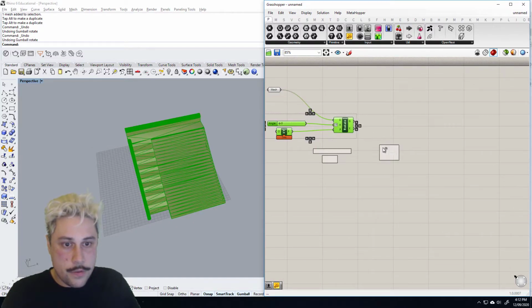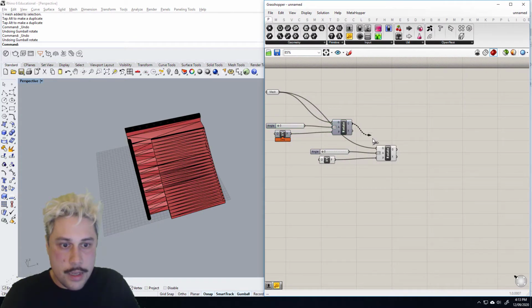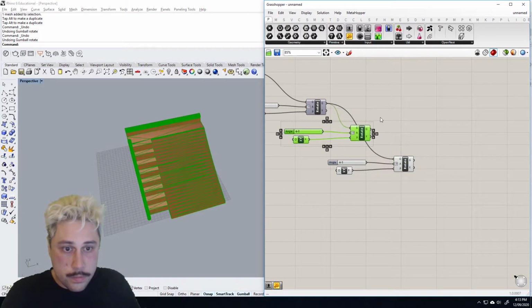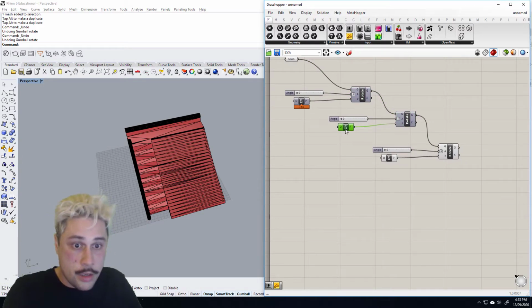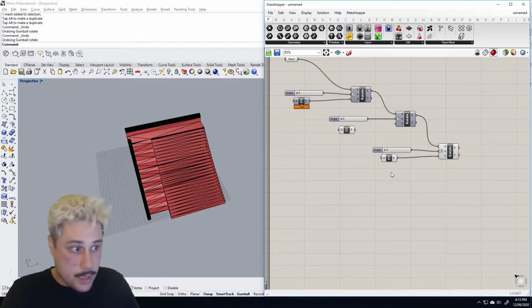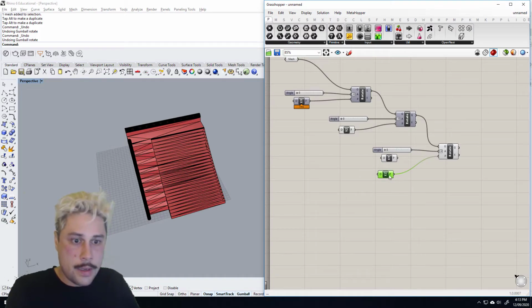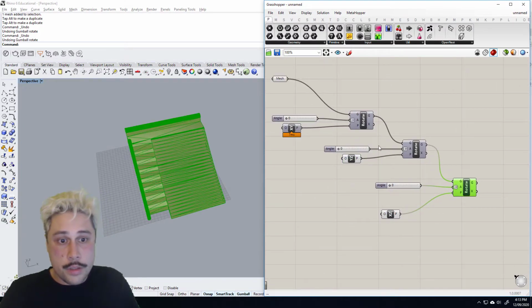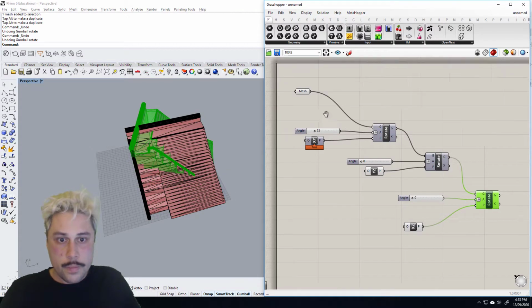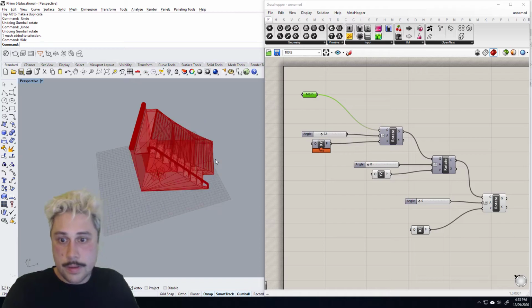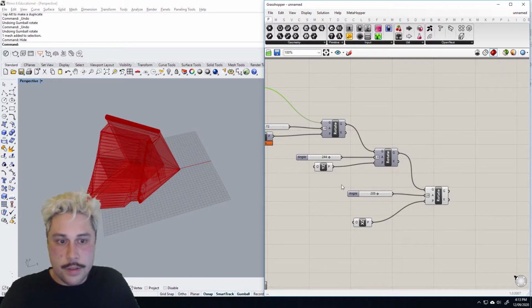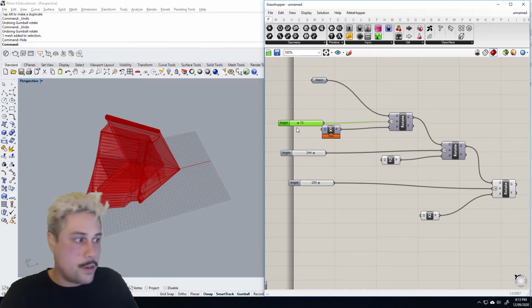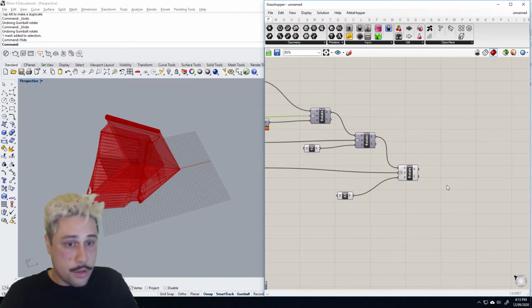And then we're going to daisy chain a few of these together. We're going to take that result and rotate it, except we're going to change the plane to be YZ and then XZ. So the result should rotate around like that. I'm just going to hide this one. And then it'll also rotate like that, and also like that. So essentially we have three kinds of angles that we can rotate this box around, which is great.